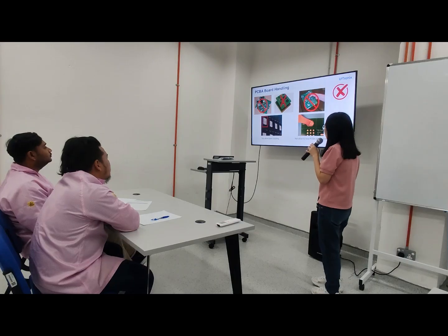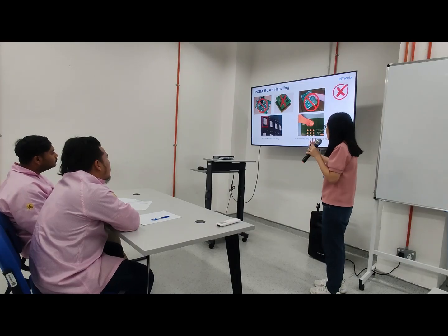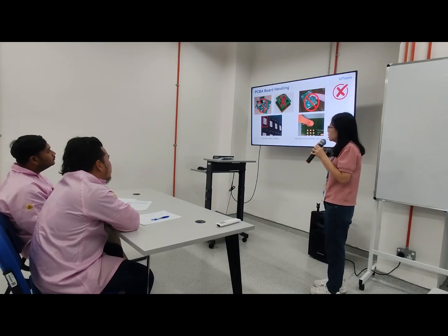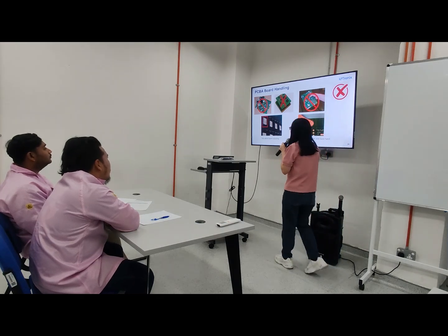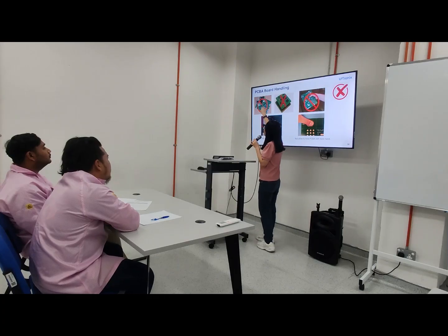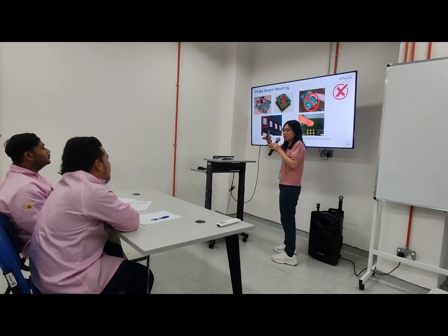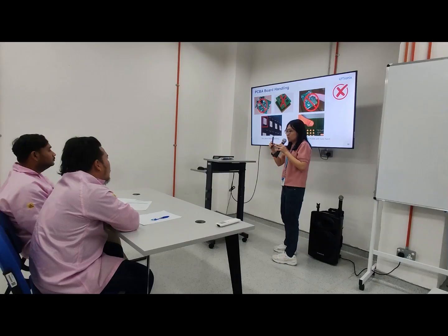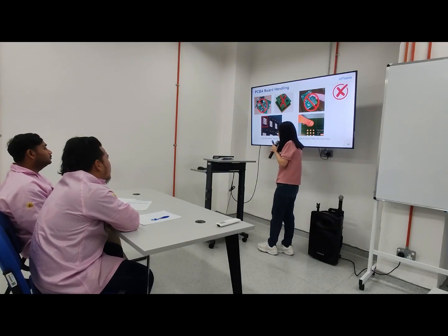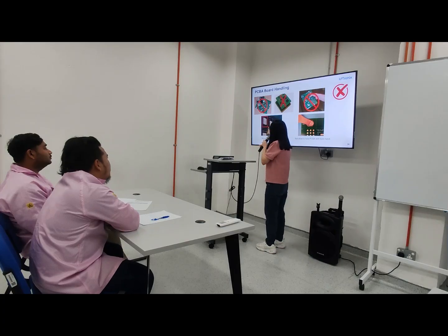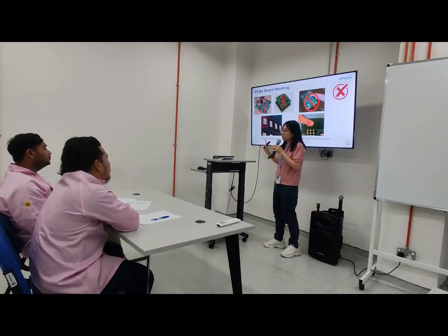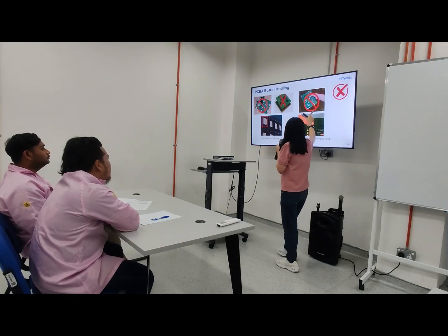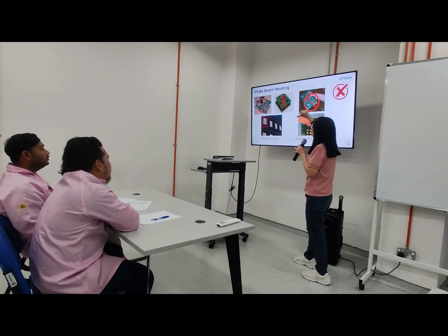Okay, next is the PCBA handling. This one is PCBA level handling. These are all the wrong handling methods. Stacking one board and another board together. This is totally not allowed. Moreover the components might come off. This one is also stacking inside the tray. Supposedly this slot is just for one module. They are stacking like this. Cannot. This one, what's the problem?